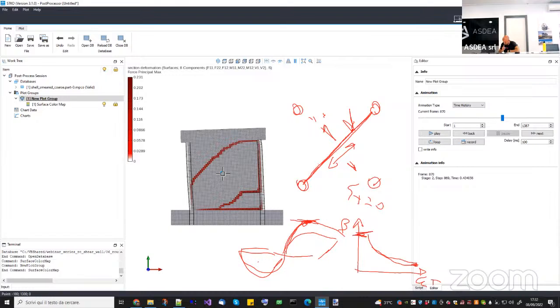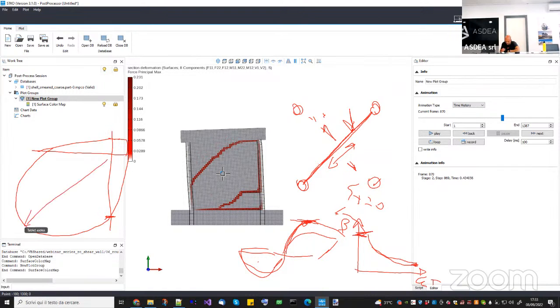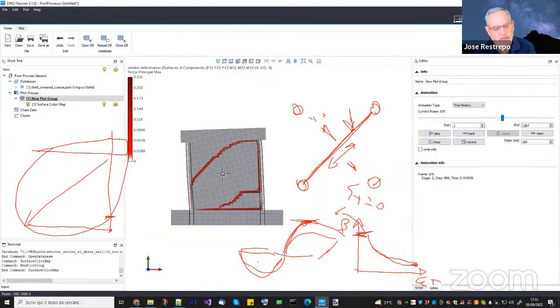Okay. And then I didn't read about it, but do you manage to have an increase in biaxial compression? Because what we have, for example, in the three-dimensional model is that, well, the typical surface is something like this. Yes. So this one is the compressive strength. Now, if you load it in biaxial compression, you have a certain increase here. But actually, I've seen that if you don't have too much vertical compression, it is not important. The effects of confinement are explicit. They don't change during the analysis.